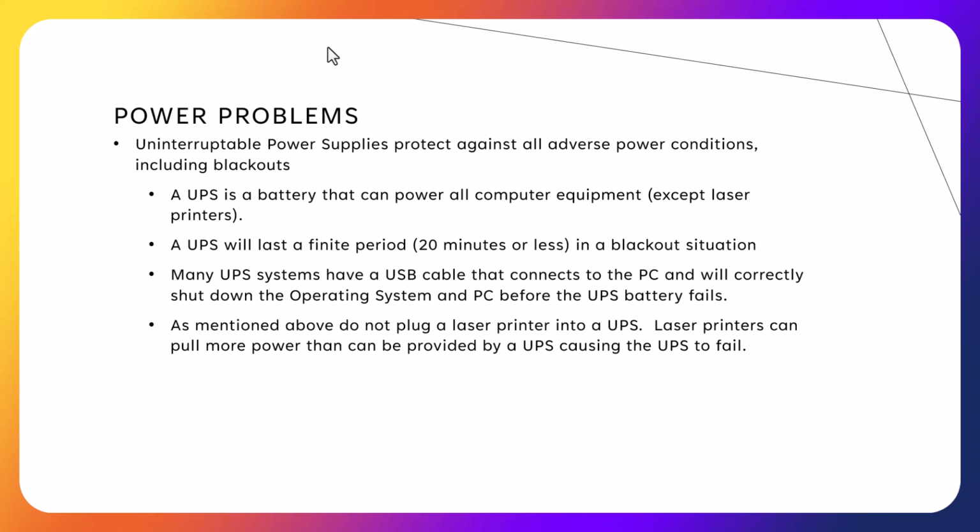A lot of times a UPS will have a USB cable you can plug from the UPS into your PC and run a piece of software. As the UPS's power drops lower and lower and it's about to lose power altogether, it will actually power down your PC to prevent any damage. Again, don't plug a laser printer into a UPS. UPSs are not rated for these lasers. These lasers pull a lot more power than an inkjet printer, monitors, or a PC.